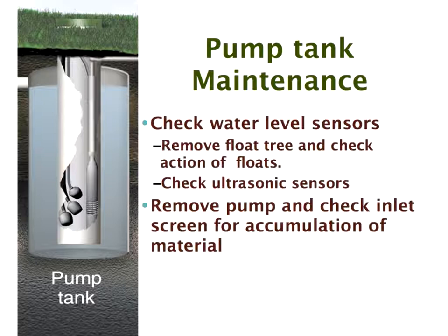There are all types of sensors today, but I think there are sensors that measure pressure. There's one sensor that's quite popular, which lies down here, and it's measuring the pressure of the water, and those need cleaning periodically. So that should be checked. Remove the pump and check the inner screen.